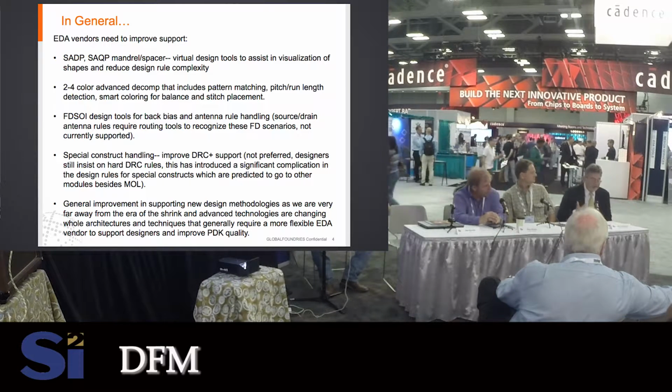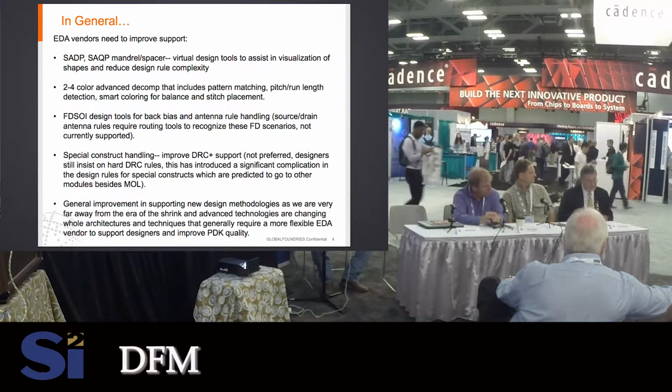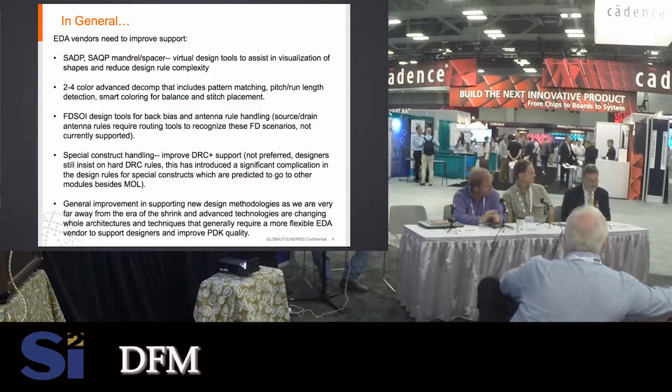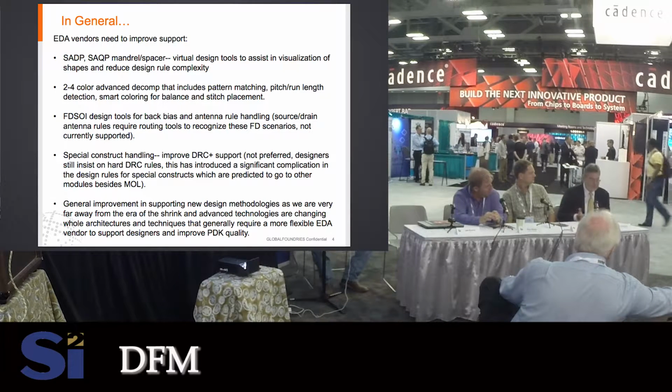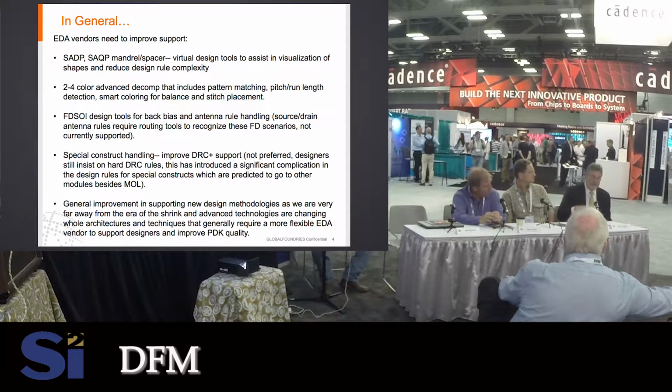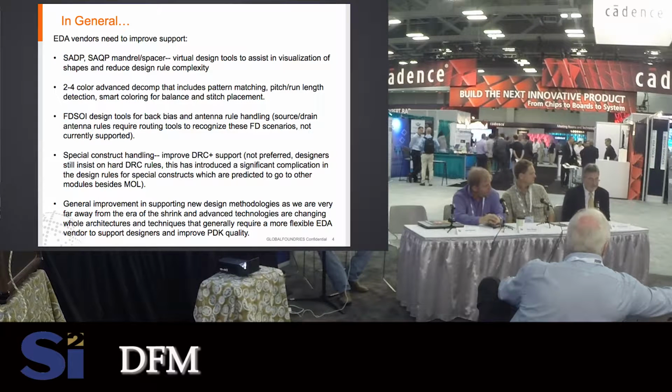The other one is decomposition. If you decompose things, sometimes things can get a little bit simpler. So if you know that things are colored, if you know that you have cut masks, and so on, you can check those, which is typically easier than checking the original artwork, which is what you get from your designer when things are not colored. So you're splitting the problem. In terms of numbers, I don't think that is really a problem directly. It becomes a problem because of the interaction.